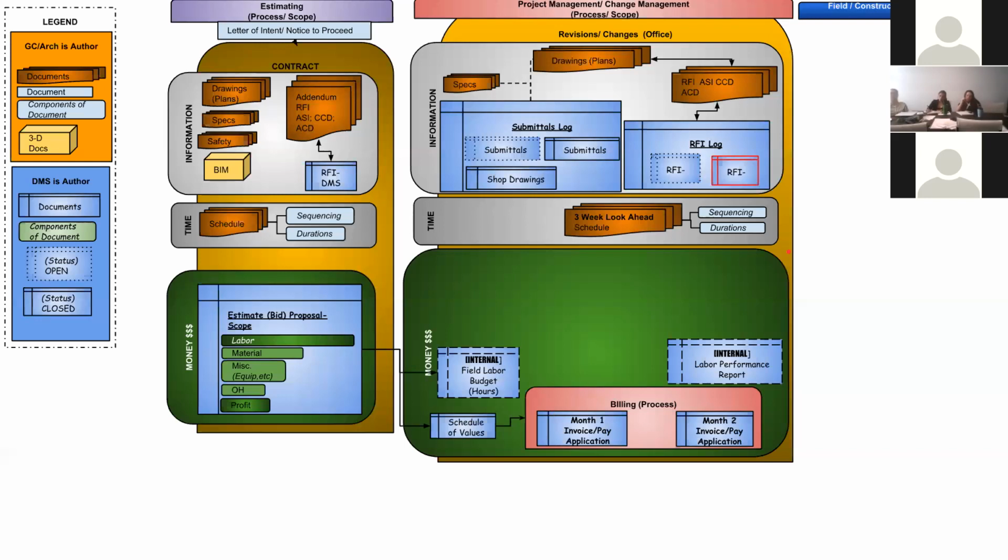So we're doing kind of a twofold item here. If no one asks a question and nothing changed on the project, it would take a certain amount of effort to manage the contract through to completion. If there's information that changes it, it modifies all these documents. This RFI modifies the drawings, could modify the specs, it modifies the schedule, and it modifies the money.